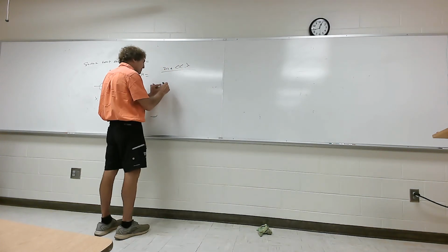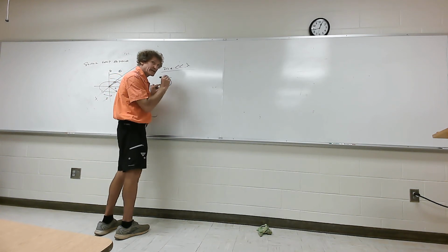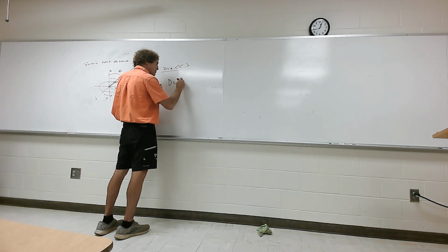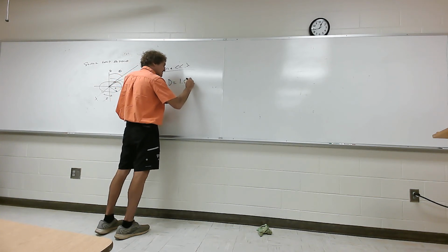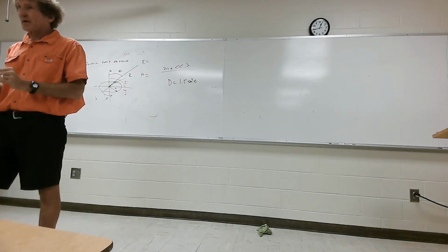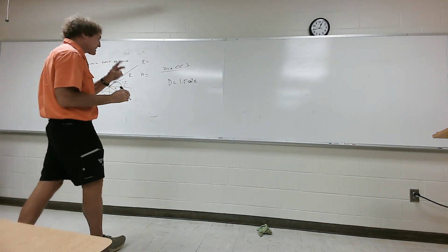Two things are important. One is the directivity of this antenna is identical to the short dipole. D is equal to 1.5 times the sine squared of theta. It's identical to the short dipole antenna. Y'all hear me? Very important to realize this. The second thing is